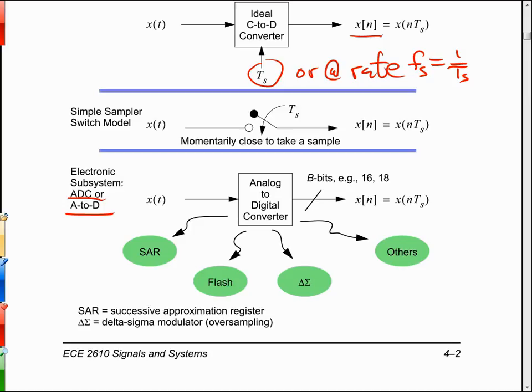I don't know if you remember the spectrum analyzer demo on Friday, but that display had graticule lines on it, and the total number of graticule lines from top to bottom, I think, is about 8. So I had it set in a mode that was displaying about 80 dB of dynamic range, and remember all the fuzzy stuff that was down there, and the spectral lines were just above it. There wasn't that much dynamic range displayed in that demo, but that was not intended to be as high a dynamic range as, say, a high-quality audio application would be.